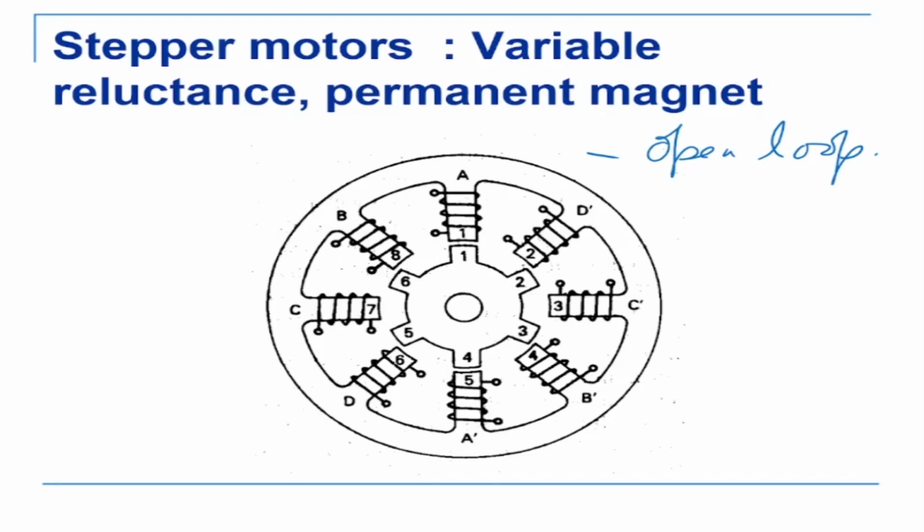Now, in the stepper motor, what we see is that this is the stator. The stator has teeth like this, and this is the rotor, and the rotor also has teeth. Now how this operates is the stator has windings or coils on these teeth. So if you activate any of the coils, suppose I give a voltage to the coil, what will happen? A magnetic field will be generated. Now this magnetic field will induce a magnetic field onto this rotor. So if it's a north-south, it will become a north-south here.